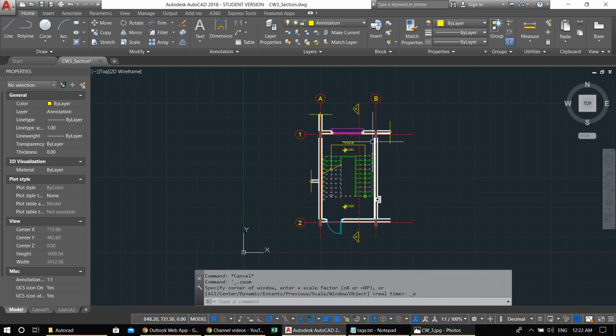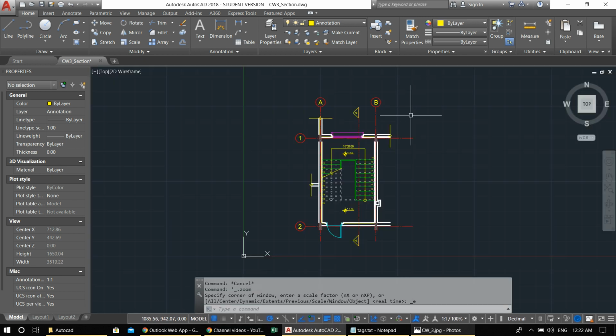You have to draw section AA, and it's very important for me that you try to draw the section AA. It will be a great part of your grade, section AA, a great part of your classwork. So you know how to draw the section. You have to draw this section in here and draw the lines. You can create a layer called guidelines and just draw all the guidelines, lock it, and then start drawing the actual drawing with the same layers.